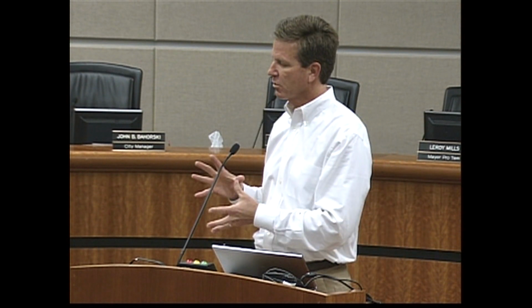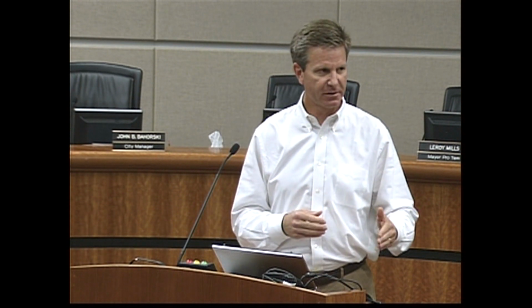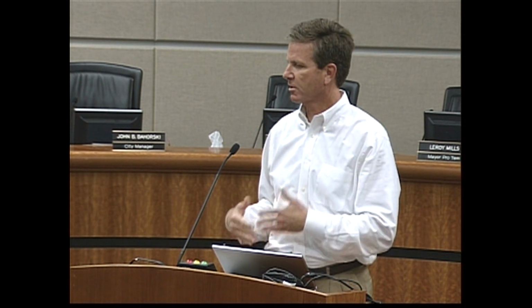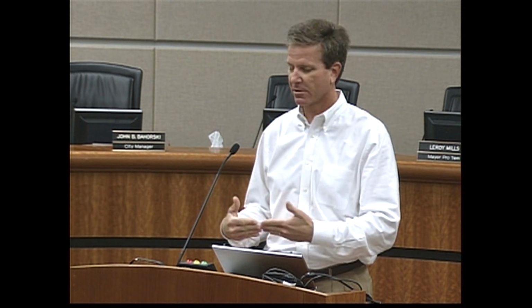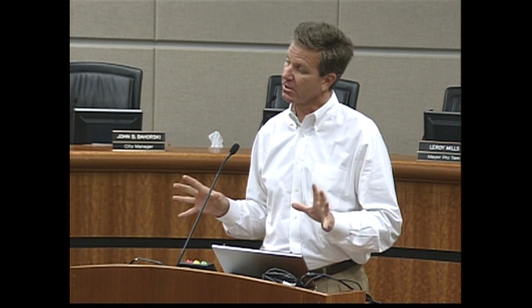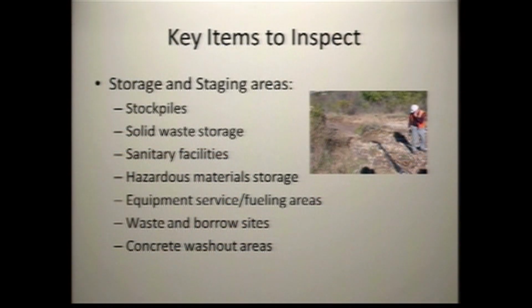Your solid waste storage, as Dan already indicated, trash containers have to be covered at the end of every day. That's to keep trash from blowing out overnight. Trash isn't supposed to leave the site. The sanitary facilities need to be back off the street. When they come to service them, they hose them out. That's a non-stormwater discharge. You don't want that non-stormwater discharge making it into the street and into the storm drain system, for obvious reasons.